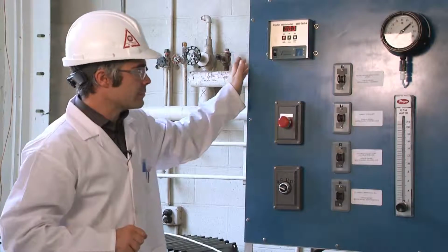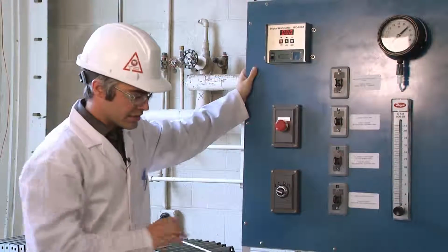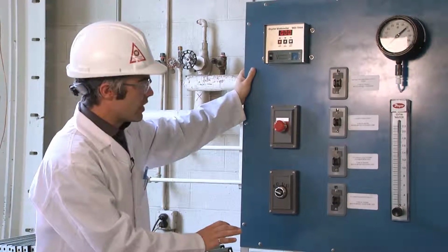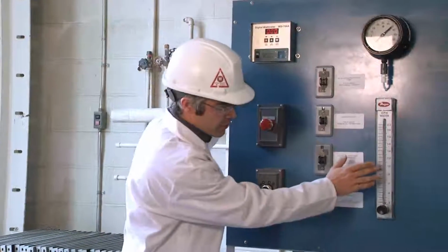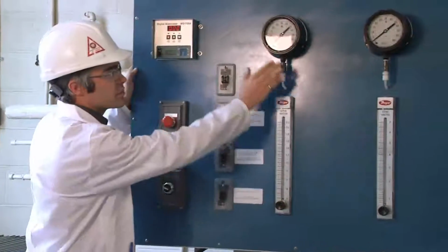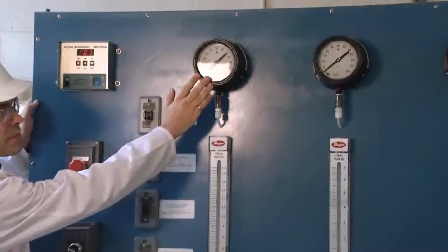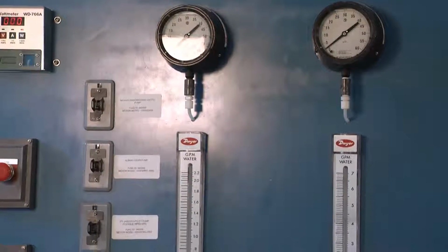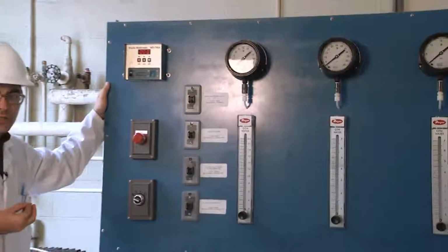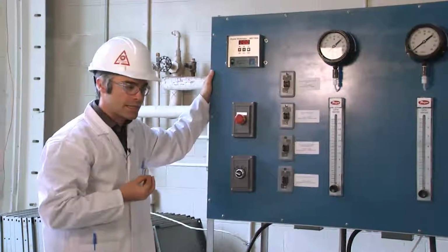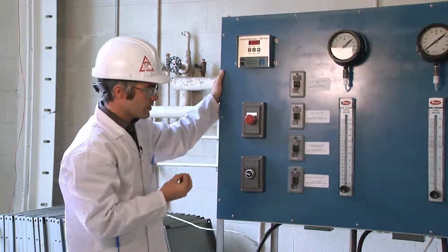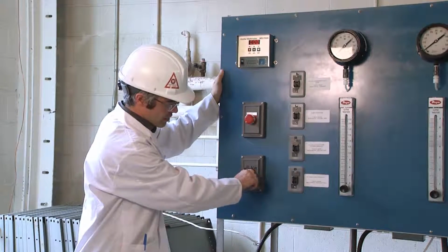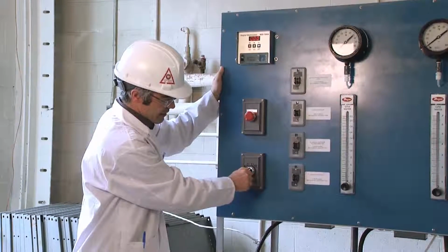In order to begin, we'll be examining the characteristics of each pump by looking at the amount of fluid flow through the rotameter and the pressure at the inlet of the pump in PSI. Make sure that you recognize whether this is gauge or absolute, and use it accordingly in your calculations. We'll be selecting through 4 pumps, 1, 2, 3, and 4.